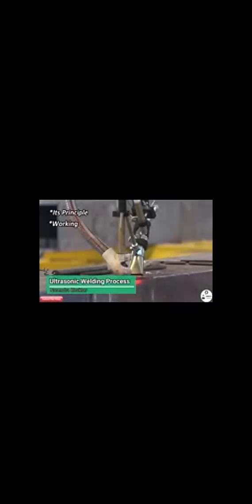Today we will learn about ultrasonic welding, its principle, working, and equipment. It is a welding process in which ultrasonic waves or vibrations are used to generate heat for welding. Ultrasonic means vibration waves which have a frequency above the normal hearing range, about 20,000 to 30,000 Hz. It is a solid-state welding process. Solid-state welding is a welding process in which no external heat is added for welding.